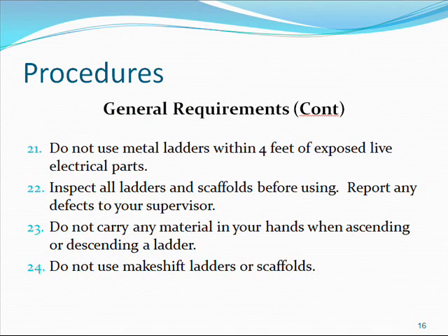General procedures. Do not use metal ladders within 4 feet of exposed live electrical parts. Inspect all ladders and scaffolds before using. Report any defects to your supervisor. Do not carry any material in your hands when ascending or descending a ladder. Do not use makeshift scaffolds or ladders.